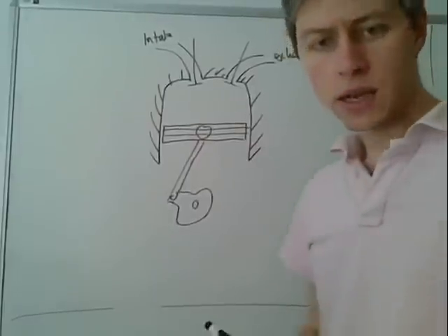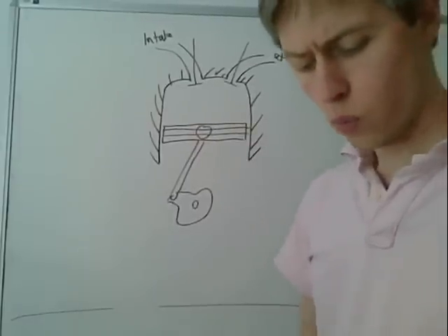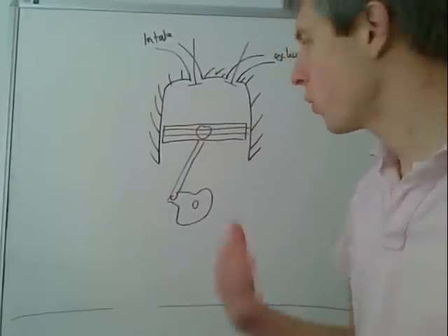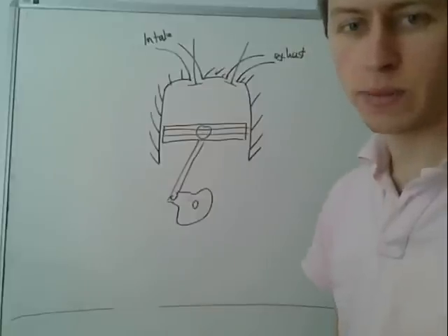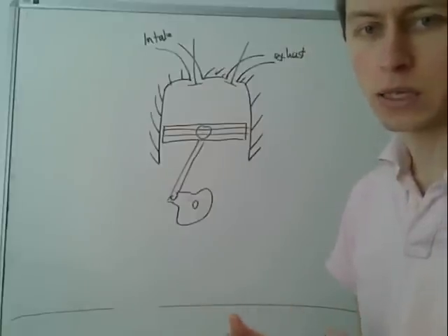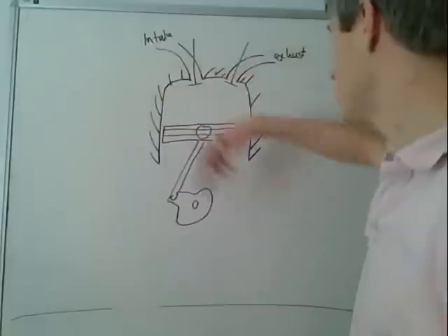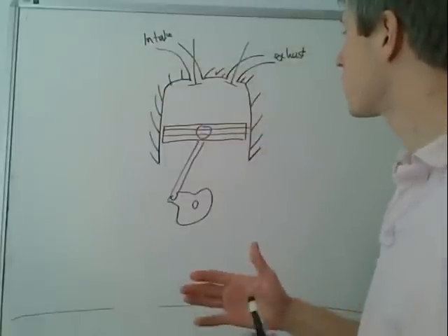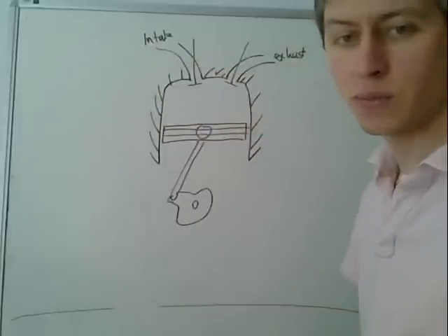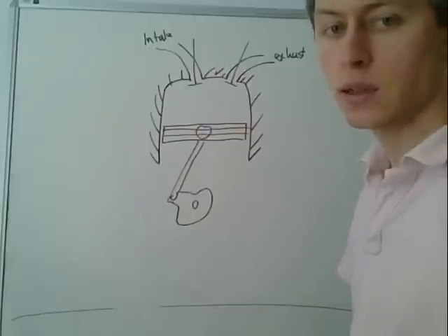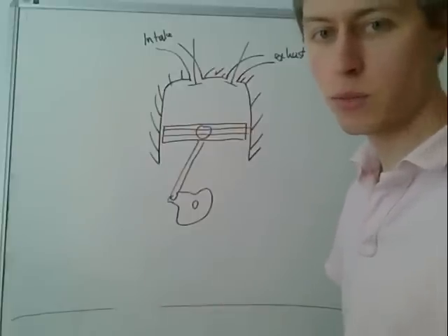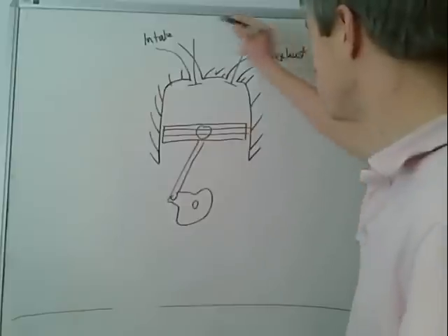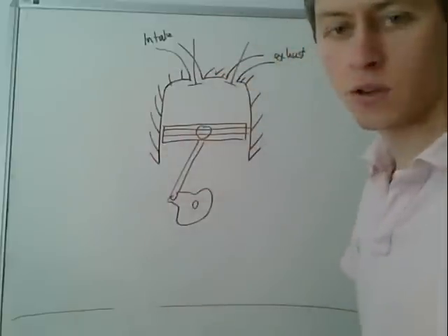So just think to yourself, where is it convenient to draw the system boundary? Because we can draw it in a number of places. We could draw it, again, an all-encompassing one, but that would mean that we had to deal with many different materials, the metal, the valve materials, different moving parts. It would be very complicated if we drew the control surface on the outside.